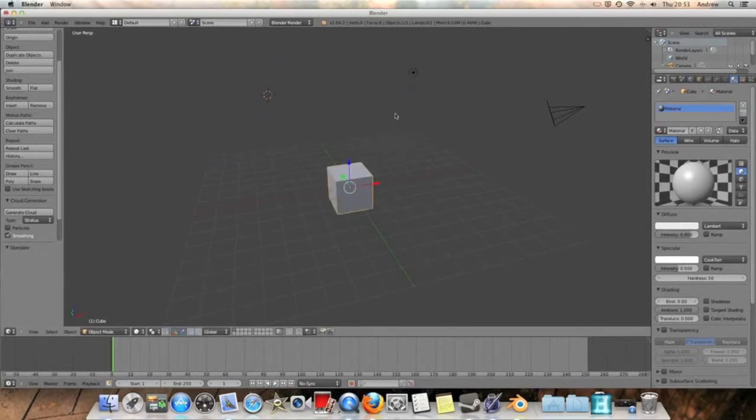Fairly basic, but of course some users don't know this stuff, so we can quickly go through all this and hopefully get more advanced throughout the next tutorials. So yeah, press G to move this. Easy way to remember that is G for grab. And then there's also rotating, and that's easy with R. So just press R to do that, and that is the shortcut for rotate.